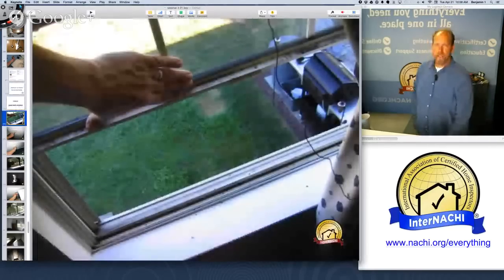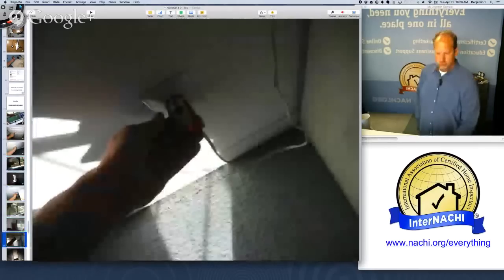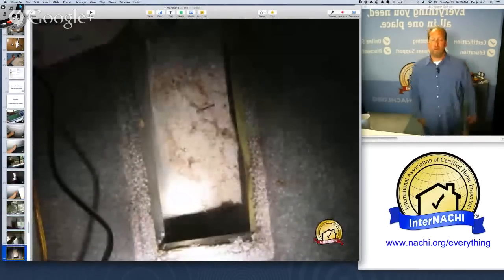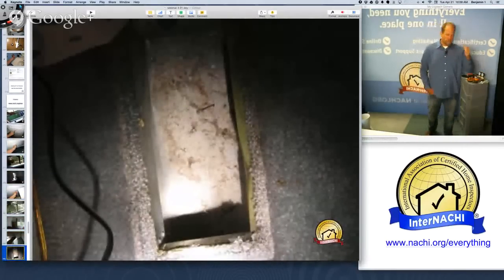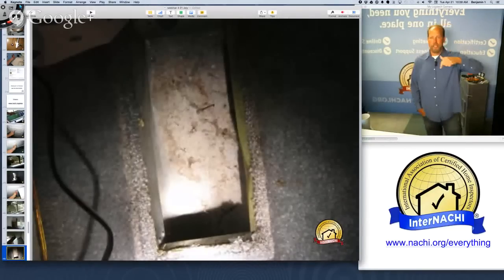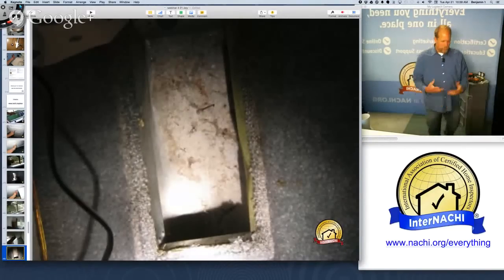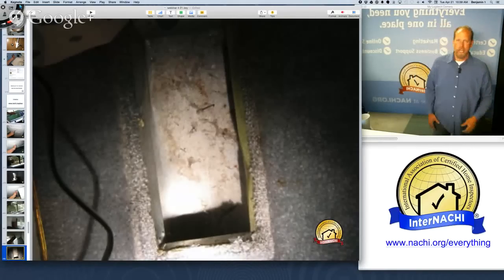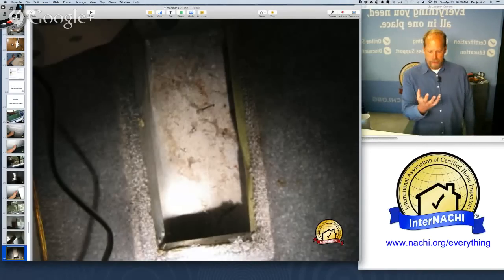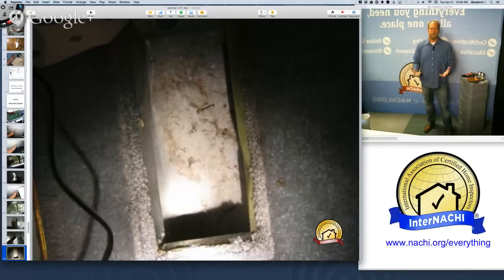Interior, very easy. Windows, doors, receptacles. Flooring, whenever there's forced air duct, I like to open up the registers, the wall registers, the floor registers, ceiling, and stick my hand in there and see what's in there. Usually I find a lot of stuff that's disgusting, so I wear gloves. But I show my client that the HVAC system is the heart and lungs of the house.